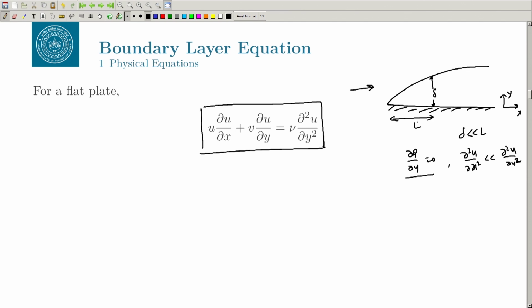We will look at the character of this boundary layer equation also. The boundary layer equation describes the flow; it is basically the balance between the viscous force and the inertial force. If the Reynolds number is very high, then the role of the viscous force is limited to a very small area. So, if the boundary layer Reynolds number is quite high, you will have the boundary layer very close to this region.